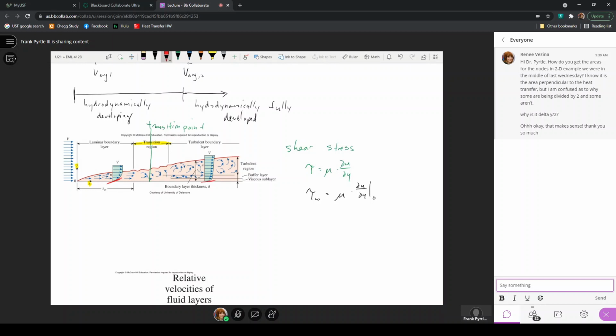These velocity gradients give us an expression of the wall shear stress that changes as a function of position. If you recall some of the calculations you may have made, you can calculate expressions of local shear stress on the wall and average values of the shear stress on the wall. The averages are needed because the shear stress varies along the length of the plate, and the reason is that du/dy, the velocity gradient at y equals 0, varies as a function of position.